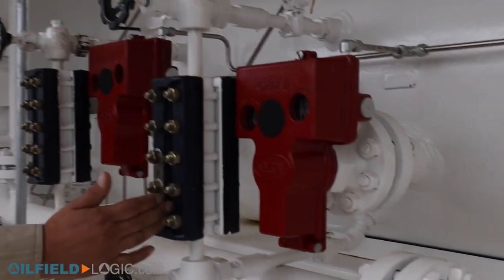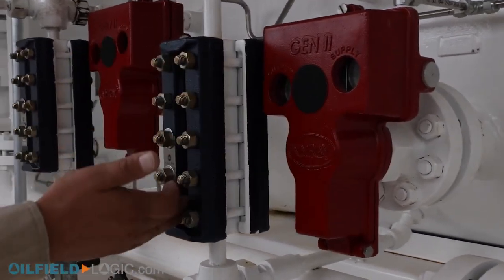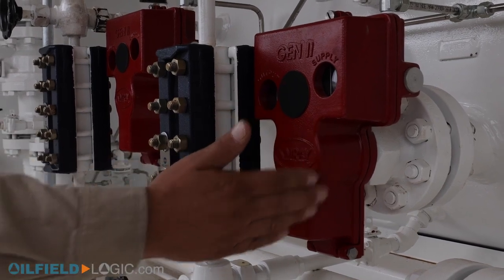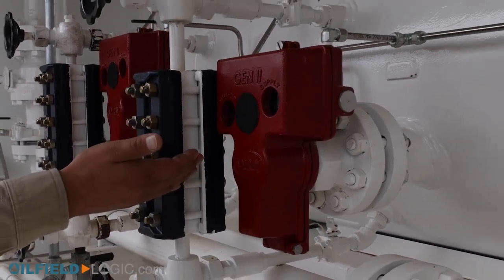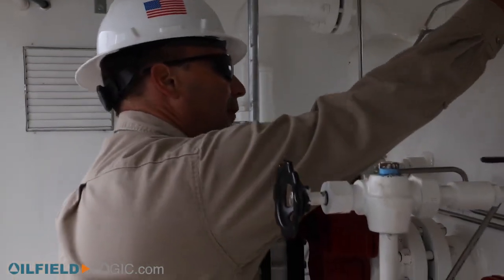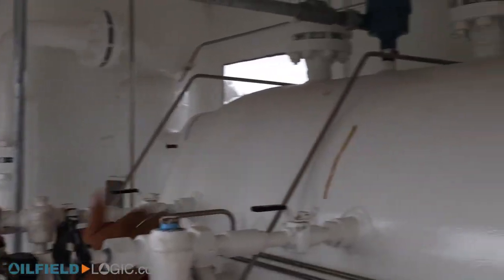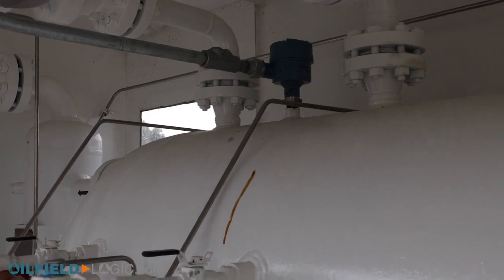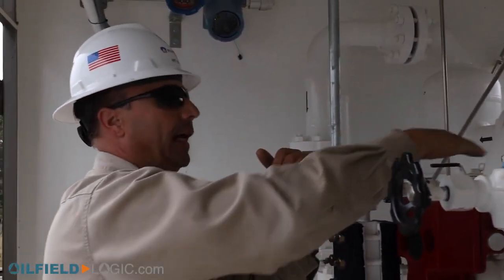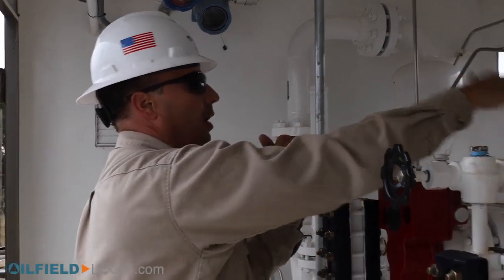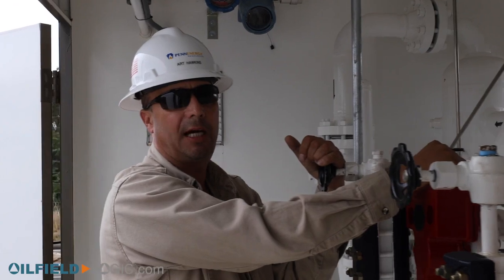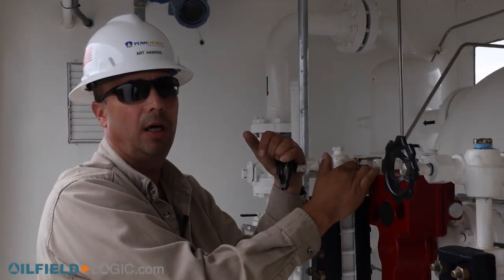We have some sight glasses here to be able to track how much fluid we currently have, and it helps us adjust the levels that we're looking to have set off of our dump controllers. We do have a device on here for a high level. If we were to have a failure of one of the dump controllers, we don't want to carry liquids over into the sales line. So if that liquid gets up to a certain level, that'll shut us down on a high level condition, send an alarm out to the operator and stop flow to the unit.